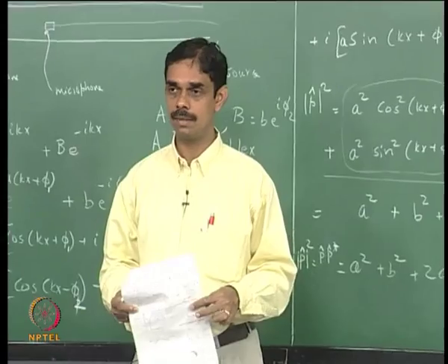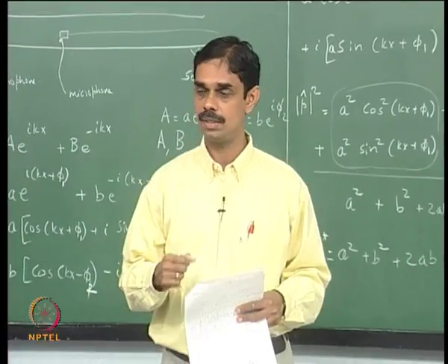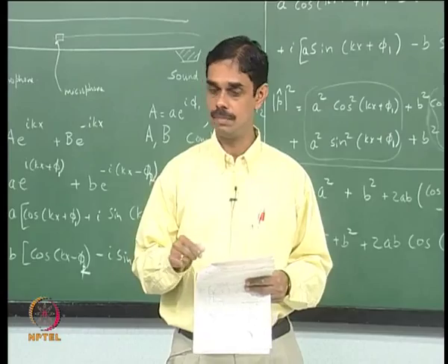So in summary, at a minima the standing wave distribution is quite sharp, at maxima it is not quite sharp, therefore we choose the minima.